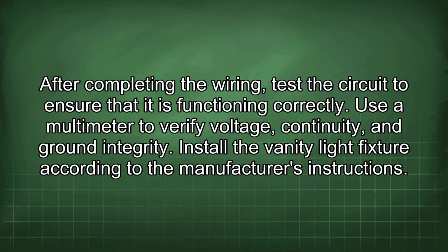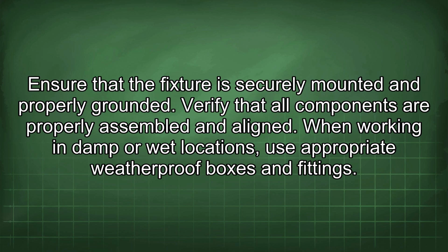Use a multimeter to verify voltage, continuity, and ground integrity. Install the vanity light fixture according to the manufacturer's instructions. Ensure that the fixture is securely mounted and properly grounded. Verify that all components are properly assembled and aligned.